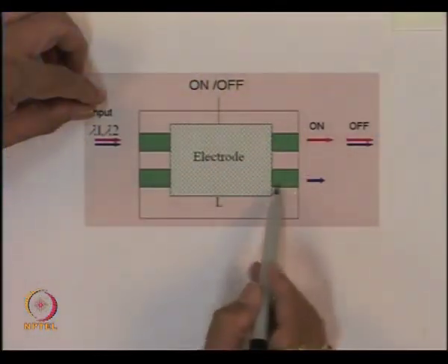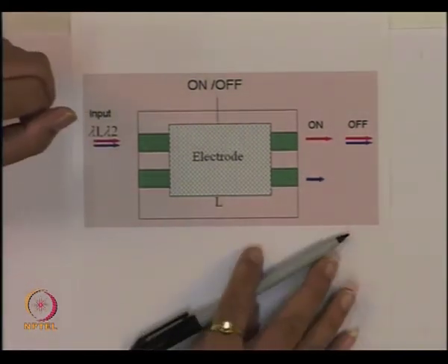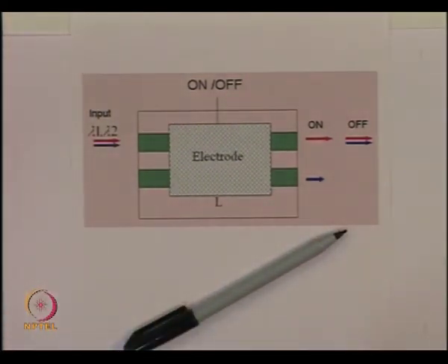dependent dropping device. So the signals were coming which are flowing on this. Essentially by applying a control signal, one of the wavelengths is dropped at this location. So in a complex WDM network where a large number of wavelengths are moving, if you want to drop a certain wavelength at a certain destination, we can introduce this device, apply the control signal in such a way that that particular wavelength can be dropped at the junction, and essentially we have created a wavelength drop multiplex.